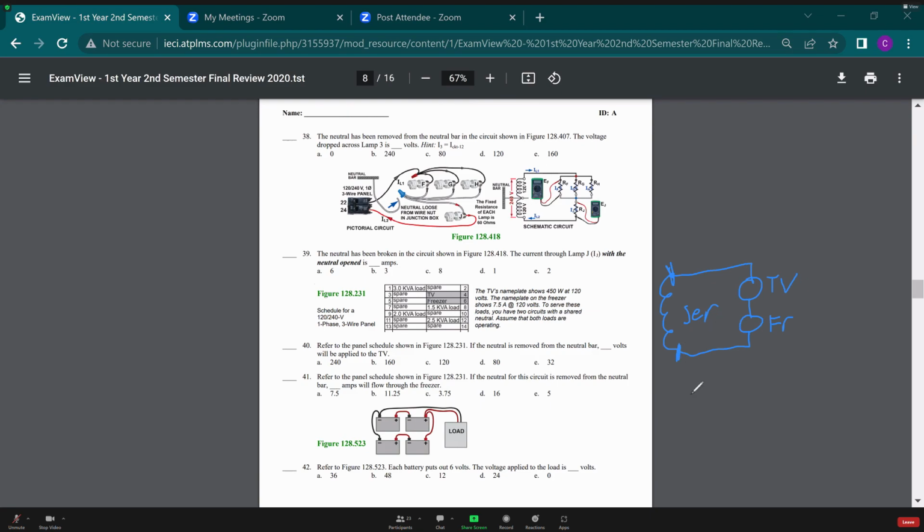In a series circuit, what I want to do is find, first off, my resistances for each of these, then my resistance total. Using my resistance total, I can find amps, and that's my apples to work off of for my whole circuit.